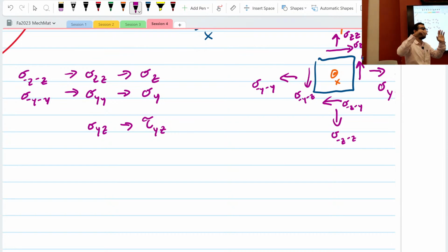We will go through this in this class. We will talk about what is an equivalent shear stress in terms of normal stress. And in many cases, what you'll see is that you need only half the shear stress that you need of the normal stress to cut something or to break it.